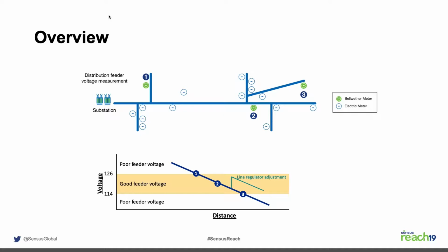And so oftentimes there's additional equipment that can be used on the distribution network to make sure you stay in those bounds. Now, in order to supply power at this level, generally it costs more to generate at this level here. And so the whole notion of conservation voltage reduction is how can you keep the end of the line within the bounds while at the same time lowering this as much as possible. That's in an effort to reduce the amount of power that you guys are purchasing. And so more or less that's conservation voltage reduction.